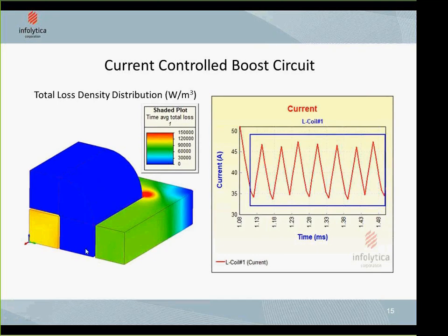And this is a good and practical assumption: if you have well designed the inductor, then it means you have been able to suppress your AC losses, and you are left with only the DC losses. So to be able to estimate my DC losses on the winding, it will uniformly distribute the current within the turns. Now I can analyze my core, or design my core, appropriately.